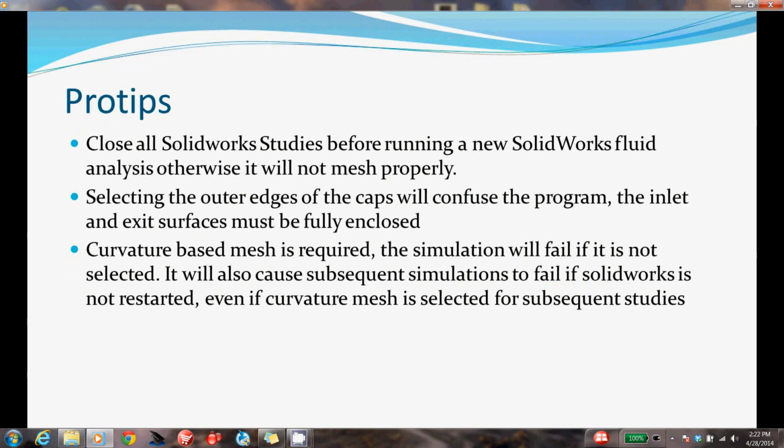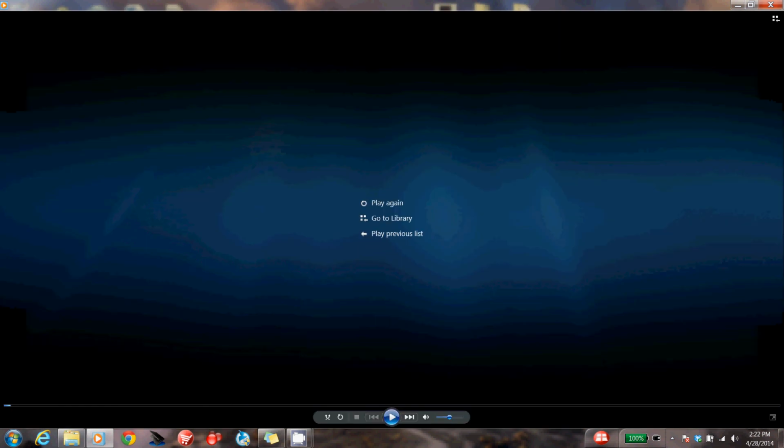Our pro tips, like as I said before, close all the studies beforehand. The outer edge of the cap will confuse the program, and the curvature-based mesh is required. Thank you, and I wish you all the luck with your thermal study.